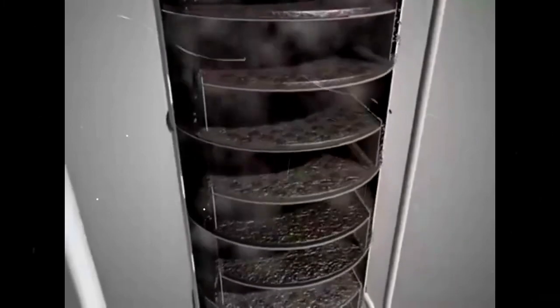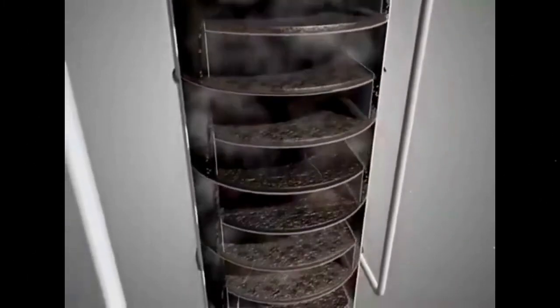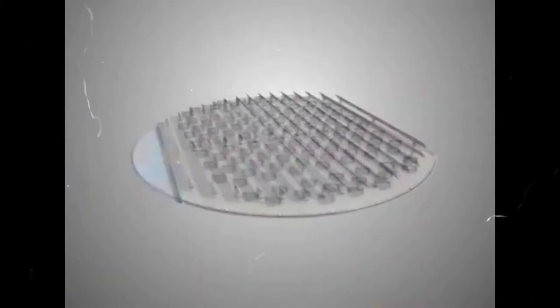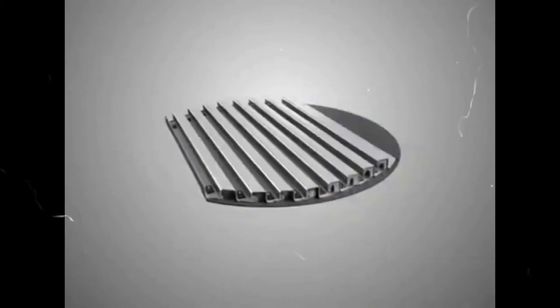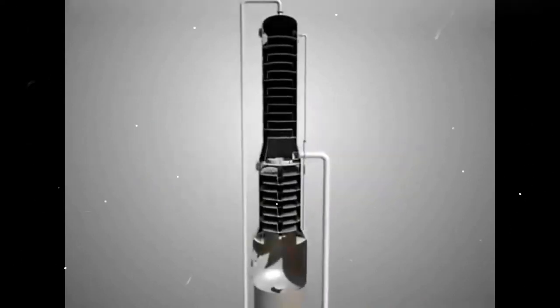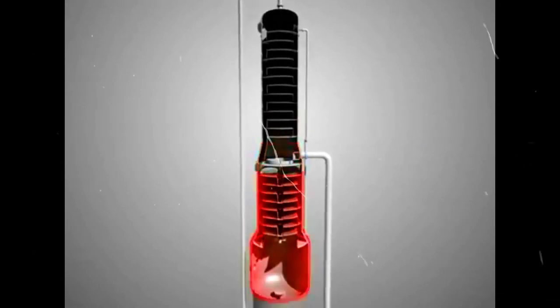As the liquid flows across the tray, vapor passing through the perforations in the tray surface forms a froth on the tray surface, which allows mass transfer to take place. At the outlet from the tray, the froth spills over a weir subtending the tray into the downcomer. The downcomer is a device for transferring the liquid phase downward to the next successive tray but is sealed by such liquid against the vapor passage upward.